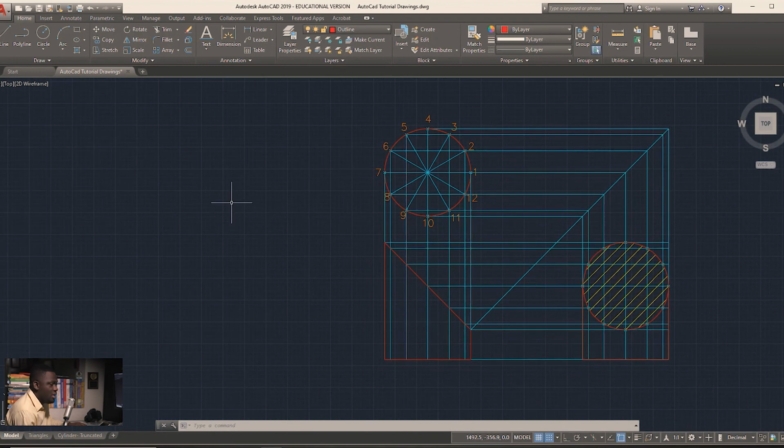The development is the unrolling of the object. If you had a sheet of foil paper and you rolled it into a cylinder, and you could look through one end. Say you took a pair of scissors and you cut across that paper. What type of pattern would be formed if the foil went from end to end and you cut across at 45 degrees and unrolled it? That's what we're going to draw now. That is called the development.